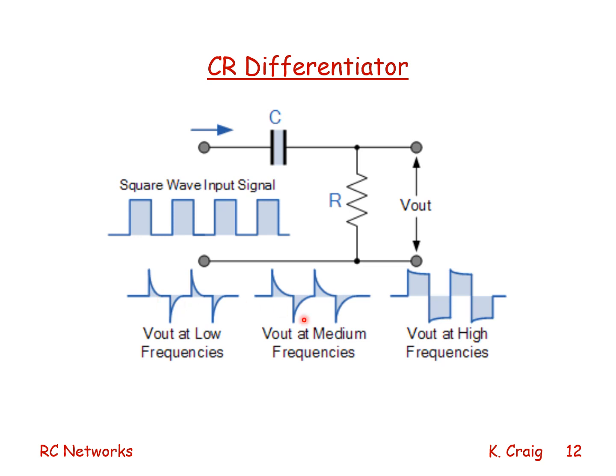I do not see that at medium frequencies or at high frequencies because the CR circuit does not behave as a differentiator except at low frequencies.